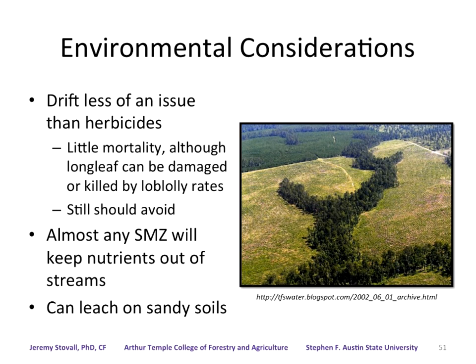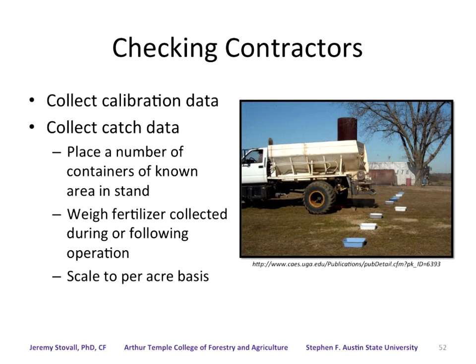There is some evidence on sandy soils, such as the Sea Tree site we focused on in the last webinar, a deep sandy soil down about 10 feet, where they've applied a lot of fertilizer and can't quite account for all the nitrogen. One theory is that on some of these sandy soils, we may be leaching some of it out the bottom of the soil profile. But again, that's a relatively small percentage of our sites. And even there, if you've got a deep sandy soil, you've got deep-rooted trees, so they're probably getting the vast majority of the nitrogen that's put out. So nutrients moving off-site doesn't tend to be much of a concern with forestry.